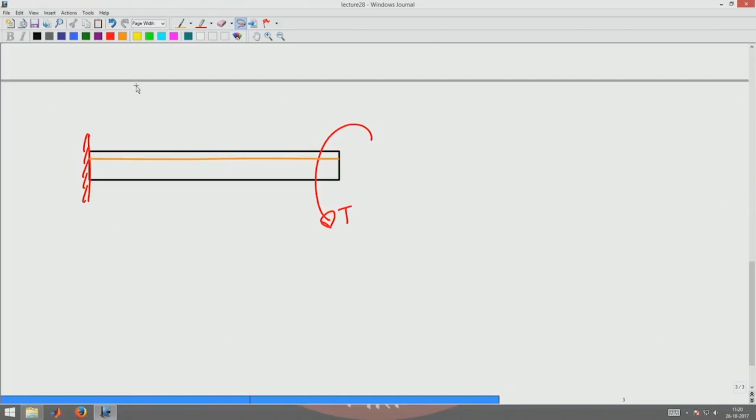This straight line is now going to deform into an inclined line, because I am assuming the displacements are small. We saw when we derived the strain that we always assume the displacement components and the displacement gradient are small, so that I can use a linearized strain measure to do the calculations.